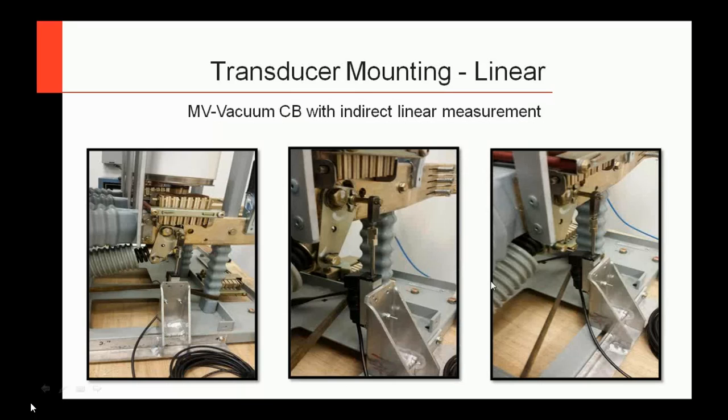One thing I'll mention is this is actually a medium voltage vacuum circuit breaker. And once again, because vacuum circuit breakers have such a small travel distance, you have to get a smaller transducer to fit in and work with what you have.